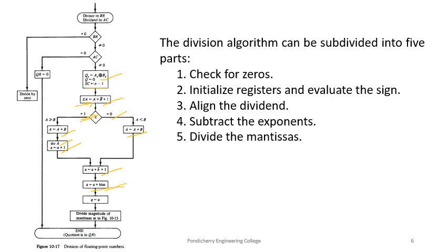Got it? Then of course A must be transferred to the small q, where your exponent is stored. And then after this subtraction of the exponent, we have to do the division for the mantissa part or magnitude part. This again is the same as the basic division process we have seen for the fixed point case.